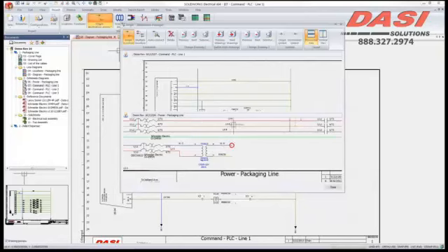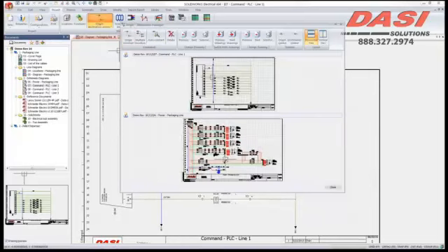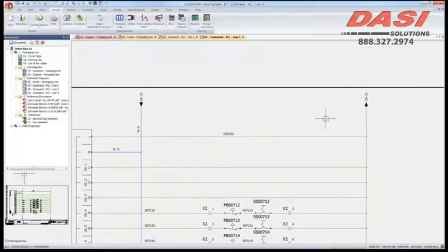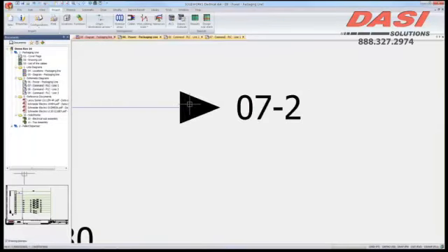Now, what you see is that I am automatically only allowed to select the proper position or same type of wire style for the design. So I can't cross-reference or cross circuitry or power by accident. I can do the same thing again here with the second one. I'll grab that. And this is actually backwards, but I want to be able to show some of this to you. Okay, so it actually bases it from your selections. Those go-to arrows still work the exact same way.